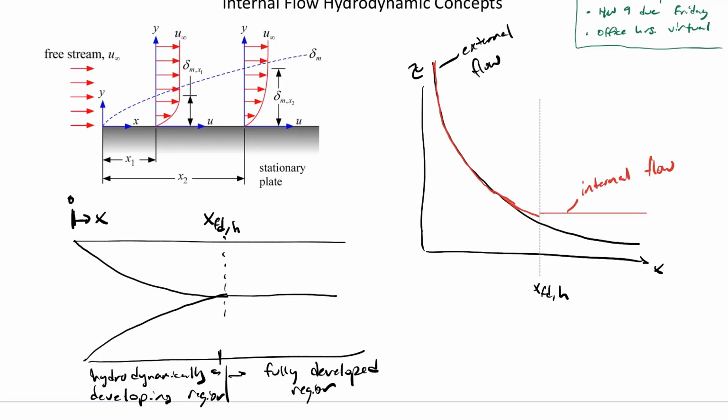So we're often going to talk about this developing region and the fully developed region. Just keep in mind, in the fully developed region, you can basically solve for a local value, and that local value is not going to change as a function of position. It's fully developed.